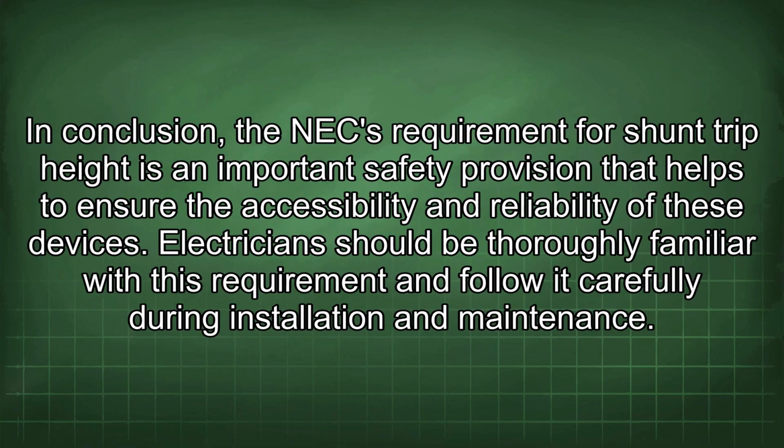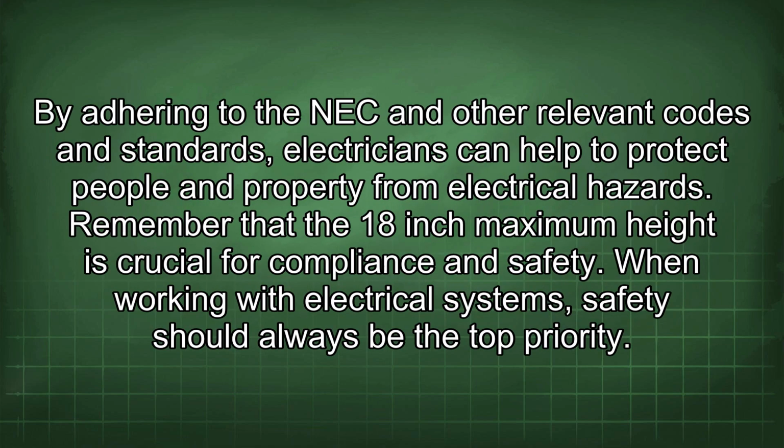In conclusion, the NEC requirement for shunt trip height is an important safety provision that helps to ensure the accessibility and reliability of these devices. Electricians should be thoroughly familiar with this requirement and follow it carefully during installation and maintenance. By adhering to the NEC and other relevant codes and standards, electricians can help to protect people and property from electrical hazards. Remember that the 18-inch maximum height is crucial for compliance and safety.